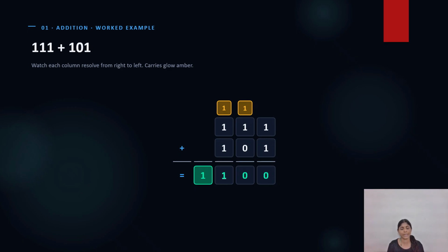So 12 is the value available there in your hexadecimal. Right? So in your hexadecimal, how you supposed to write? It is 8421 code. So 8 is having the weight 1 as well as 4 is also having the weight 1. So 8 plus 4, 12. So 7 plus 5, 12 in decimal, the same as in the binary addition. See here, 1, 1, 1 plus 1, 0, 1 is 1, 1, 0, 0. So 7 plus 5 is equals to 12 in decimal, right?